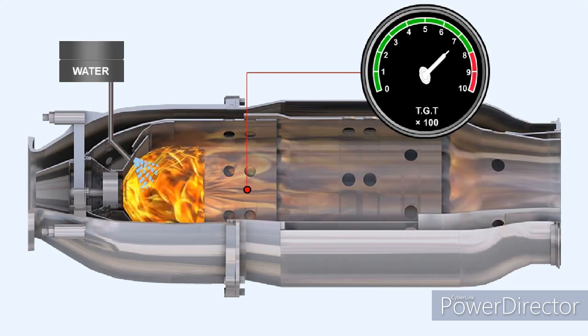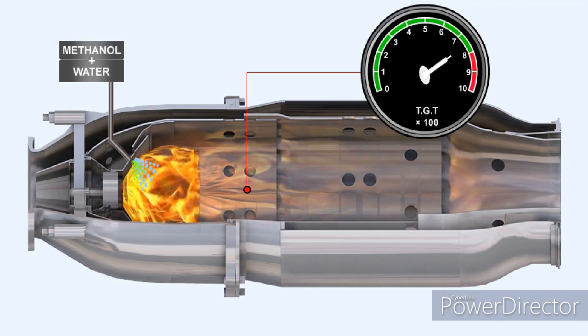By injecting coolant into the combustion chamber, the turbine gas temperature is lowered dramatically. However, if nothing was done to counter this fact, it would lower the amount of power potentially available, because the turbojet is a heat engine, which relies on there being a large temperature drop across its turbine. The bonus obtained by using methanol is that, because it is an alcohol fuel, it burns, and thus adds to the temperature of the gases, raising the turbine gas temperature back to its original level.